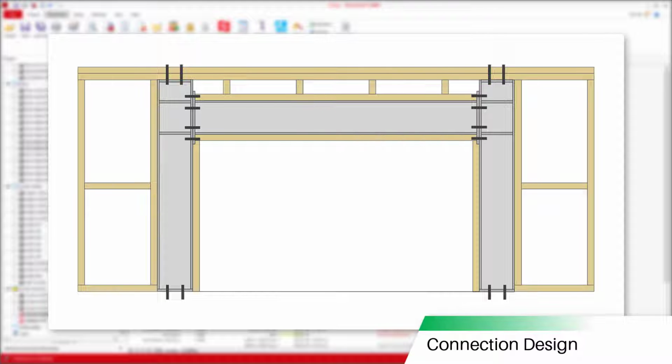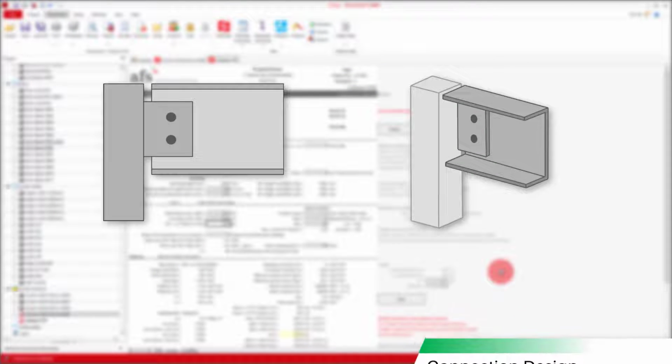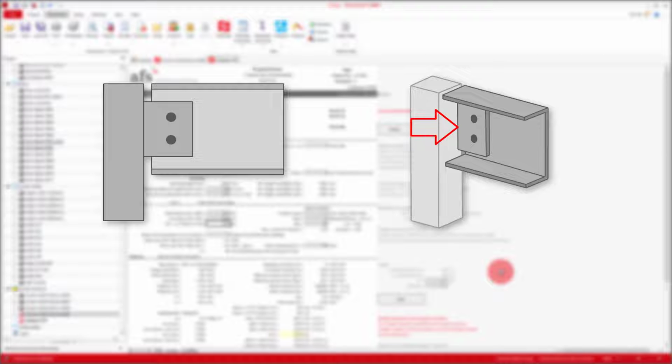But something we haven't spoken about yet are any of our steel beam and column connections. Other than the brace frame, which we're not going to do in this video, all our connections are going to be of simple construction, and so will not be transferring any moment. The way this is done with beam to beam or beam to column connections is by using a cleat plate that is welded to either a column or the web of a beam, and then bolting the cleat through the web of the supported member. As the majority of the moment in a standard section is transferred through the flanges, we can idealize this connection into one that does not transfer moment.